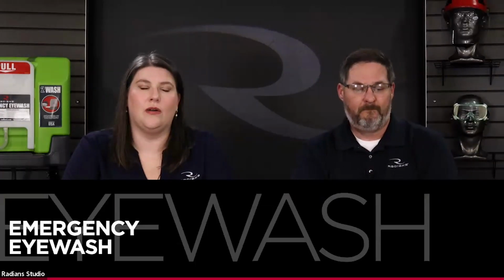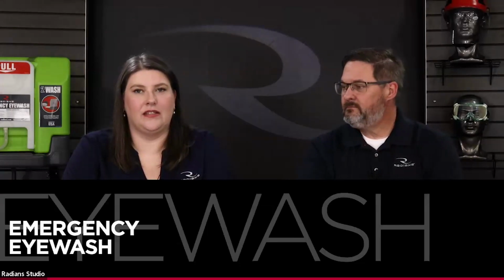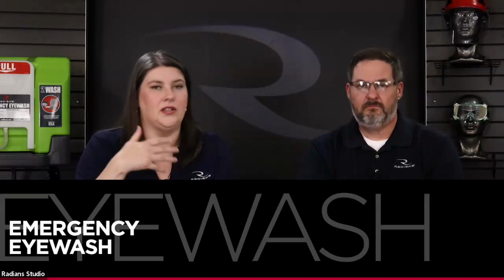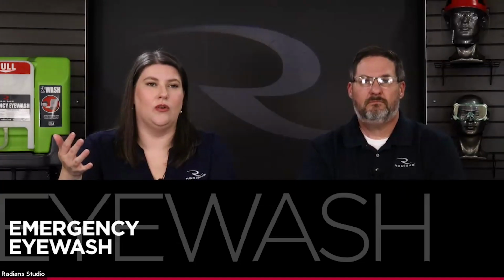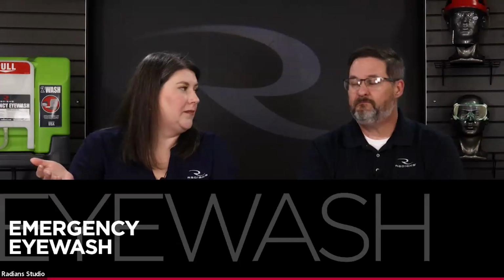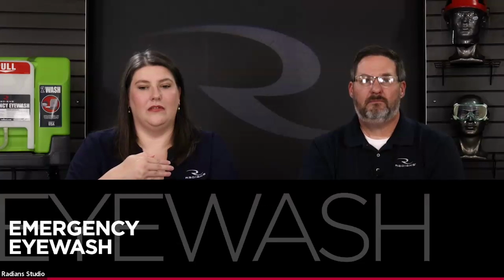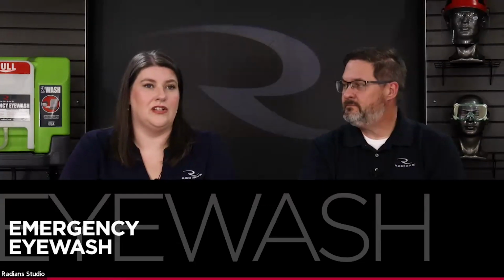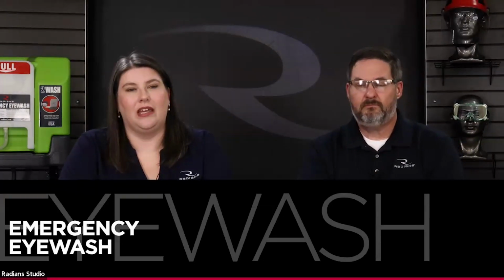Yeah, that's where emergency eye wash comes in. Safety eyewear is protective on the front end, trying to create a barrier from the chemical or projectile hazard. Eye wash always comes after the fact, so exposure has already occurred. Instead of protecting your vision from an injury happening, it's minimizing the injury that's already happening. So it's saving your vision in the event of an exposure.